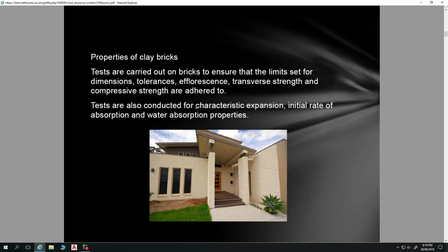A lot of these actually, that's not efflorescence as such, but efflorescence you did get a lot on a lot of these cream bricks though. Efflorescence is when you've got dissolved salts and minerals that end up coming out of the brickwork over time.